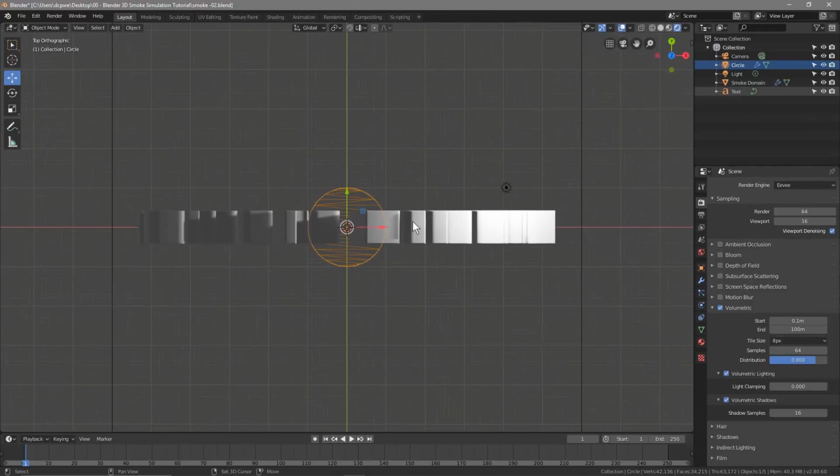We're going to press Shift and D, Shift D to duplicate. So press Shift and D, and then hit the Enter key, and then press Shift and D one more time and hit the Enter key. Now you've got 3 copies of this circle. You've got the original one, and you've got circle 1 and 2 here.